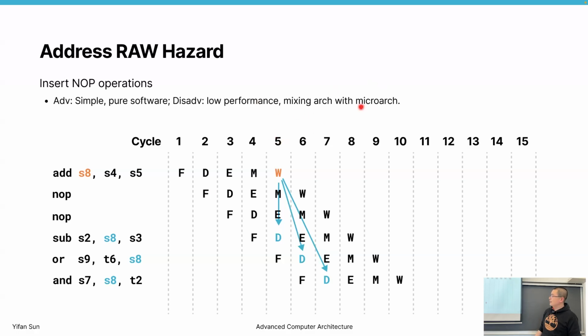And another, actually bigger, problem is we're mixing architecture with microarchitecture. Why? Because this 5-stage pipeline is a microarchitecture thing. Then you may design a 6-stage or 20-stage or 1 or 2 pipeline stage microarchitecture. If you suddenly say, oh, I'm changing from a 5-stage pipeline design to a 20-stage pipeline, you have to modify your design to add 19 knobs, right? I'm just making up this number, but the number of knobs is a microarchitecture thing.